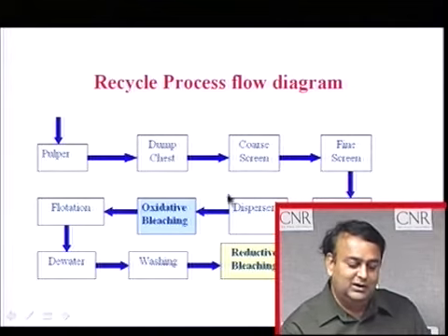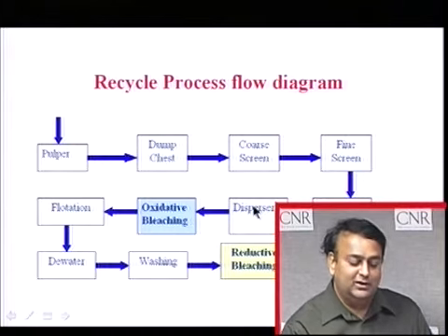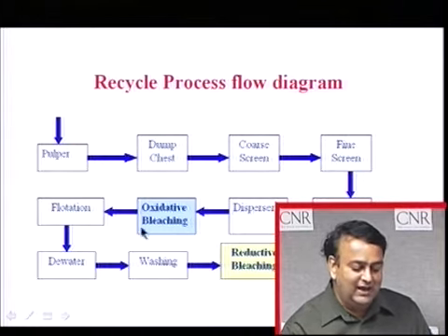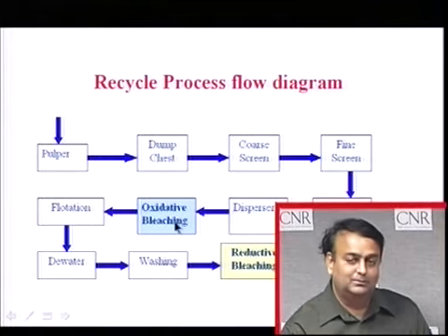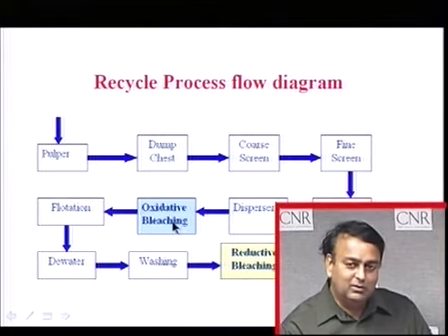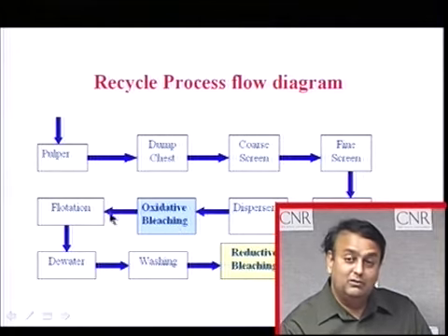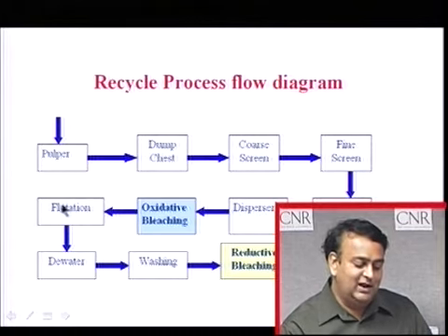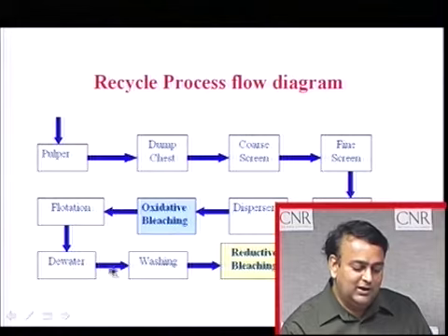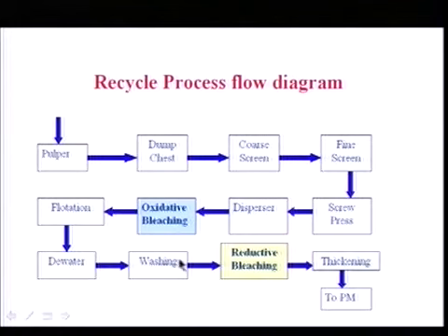The disperser is used as a mixing device, and also temperature and consistency help. Then it is sent through a retention tower where the oxidative bleaching takes place. Right after the tower, your pH will be somewhere between 8 to 9, which is ideal for flotation, and then after flotation you do the dewatering and thickening again with a washing device. Now, it is 10% consistency and the residual peroxides are removed, it is ready for reductive bleaching.